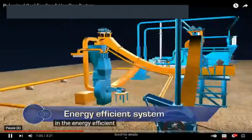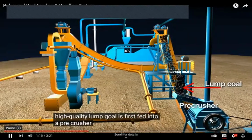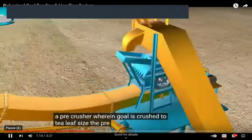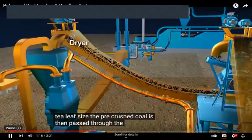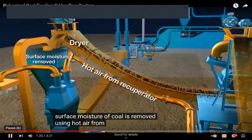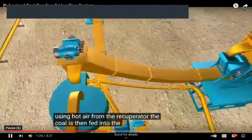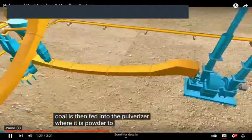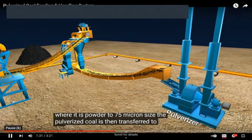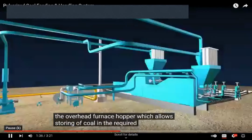In the energy-efficient process, high-quality lump coal is first fed into a pre-crusher wherein coal is crushed to tea-leaf size. The pre-crushed coal is then passed through the dryer where the surface moisture of coal is removed using hot air from the recuperator. The coal is then fed into the pulverizer where it is powdered to 75 micron size. The pulverized coal is then transferred to the overhead furnace hopper, which allows storing of coal in the required quantity